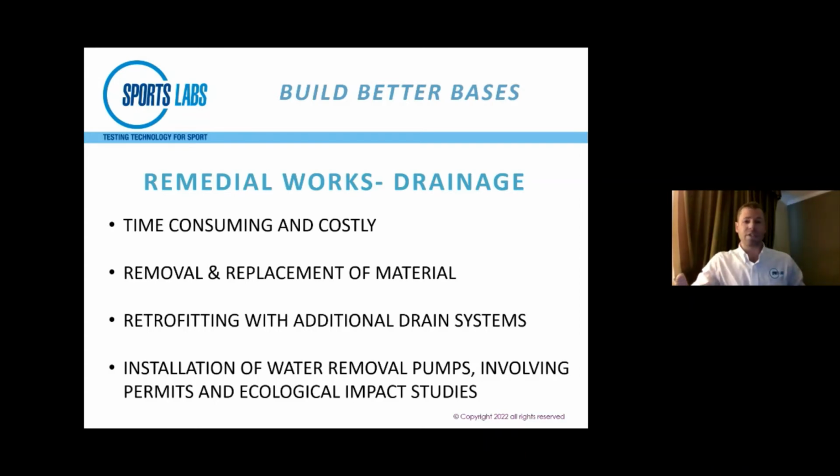To repair this, obviously it's very time consuming and very costly. It can involve removal and replacement of material. And again, this goes for whether the top layer has been installed or even before that. You might end up finding that you'll have to retrofit with additional drain systems. We've found several cases with this where perhaps the cap layer, the finishing layer, is bound so tight that it was meant to drain vertically, and it doesn't drain vertically.